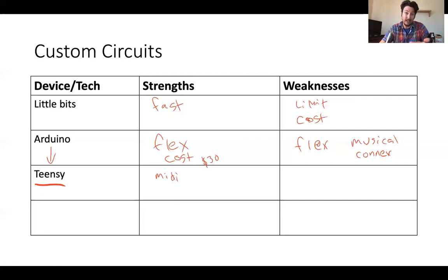That might involve a MIDI to USB interface, which adds more cost. Or it might involve rather tedious programming that makes your Arduino less flexible, because now the Arduino is kind of fixed. You can't go back and make little changes. Whereas with the Teensy, you can get in there and reprogram it, and it's sending MIDI over USB, so you don't have another device or another code base doing the translation of serial messages into MIDI. Pretty awesome.